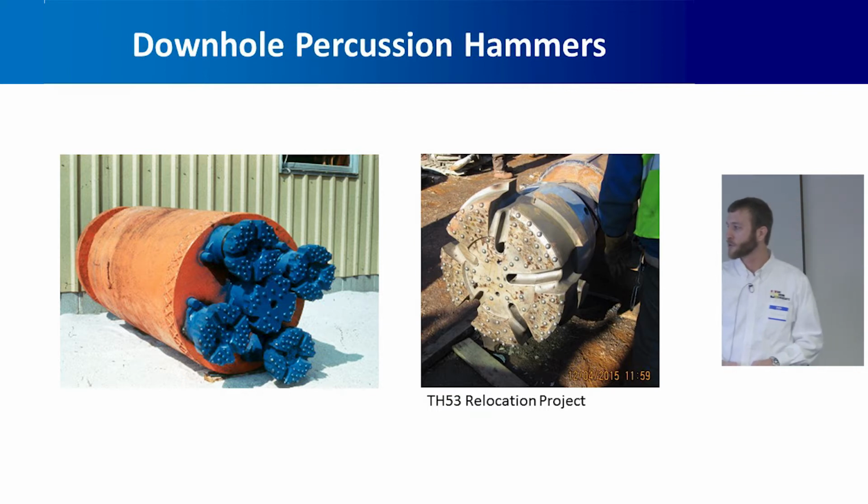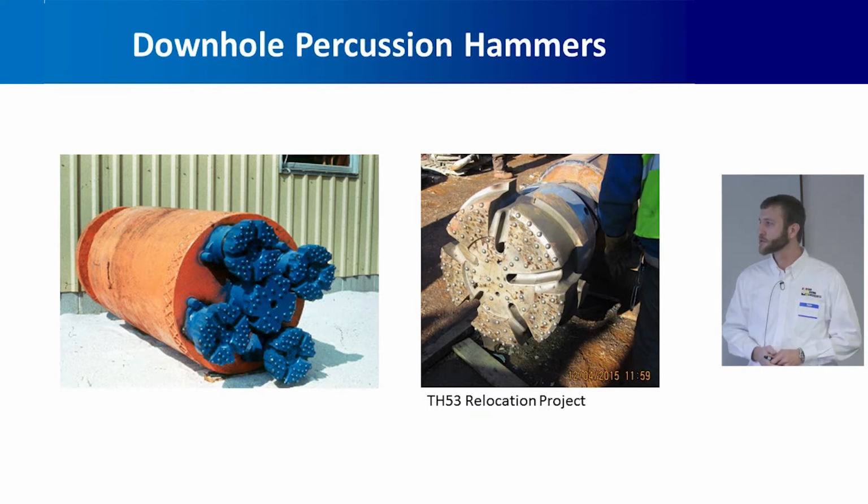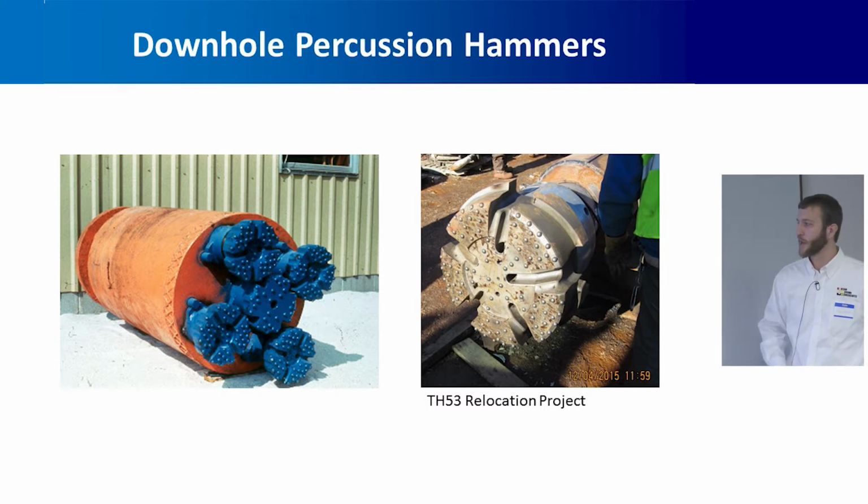For real hard rock drilling, there are percussion drills. They can be cluster drills like this, or single downhole hammers like this. This is a 30-inch drill head from the hammer used at the Highway 53 project up in Virginia.